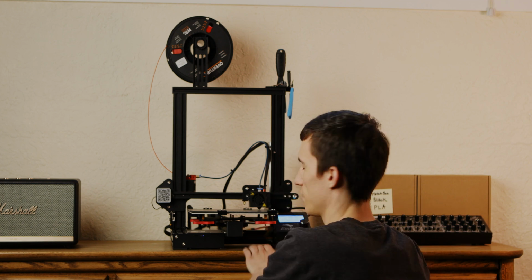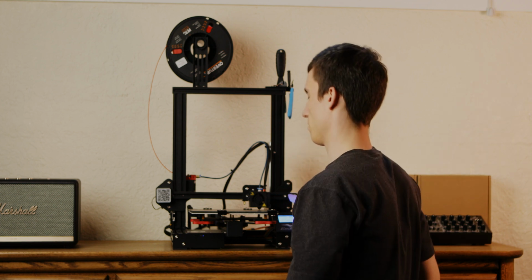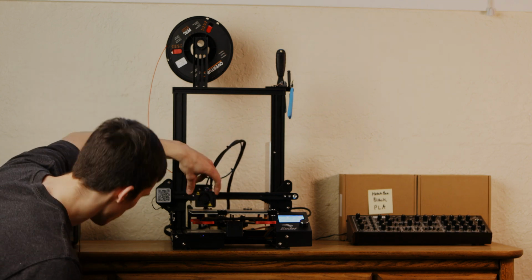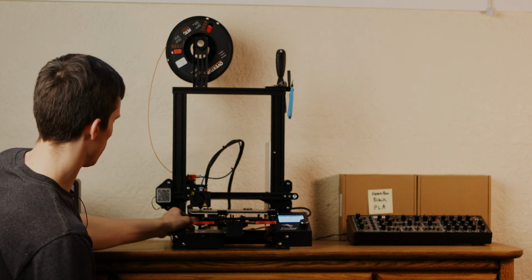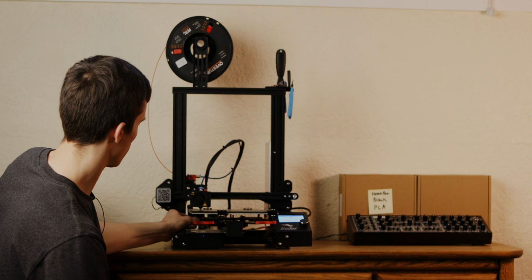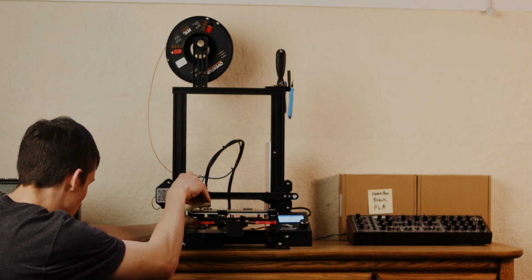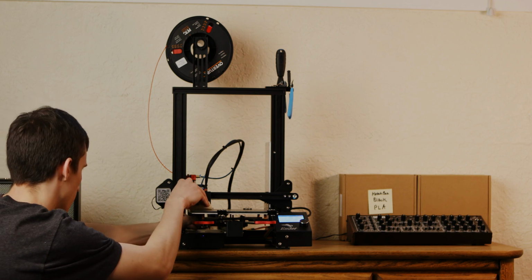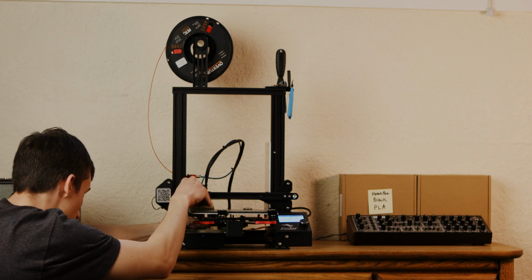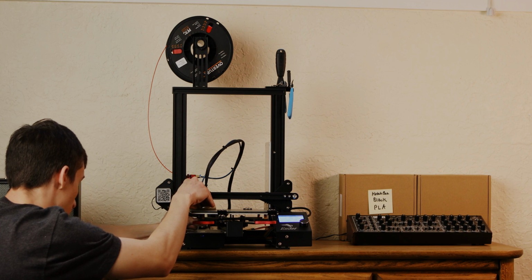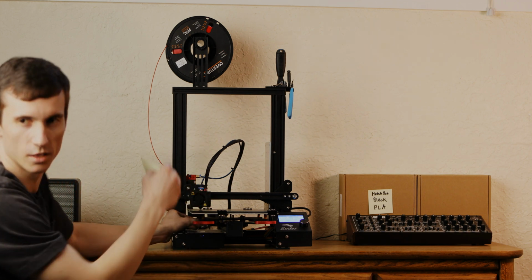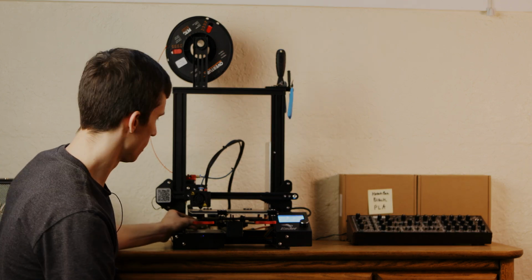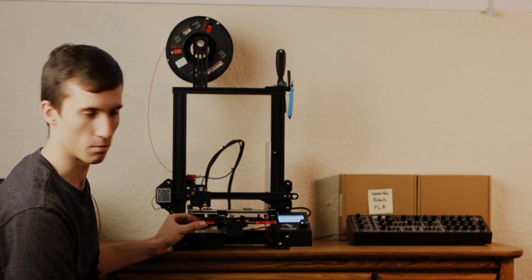And another thing the glass print beds will offer is pretty much a surface that clings on to your model as soon as it cools a little bit, like the plastic contracts, and that allows it to bond really strongly to the glass and not have adhesion issues later down the line. So what I do for each of these points is pretty much wait until I feel a slight resistance on the paper, and that's where I stop adjusting these adjustment knobs.